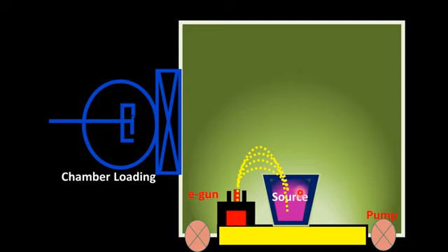There are some important facts to note. The electron beam introduced on the source material inside the reaction chamber of molecular beam epitaxy must focus at a certain point on the source material to evaporate it. If the electron beam is not focused and is somewhere near the boat in which the source material is placed, there is a possibility of incorporating the boat material in place of the source material onto the substrate, which can cause an impurity.